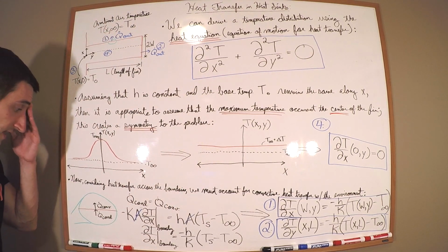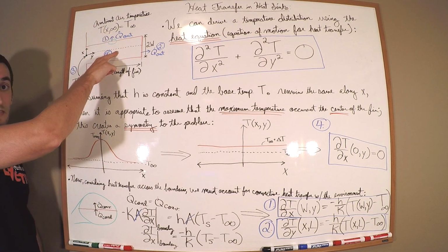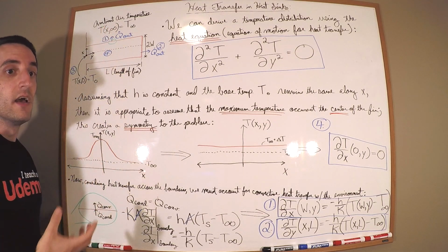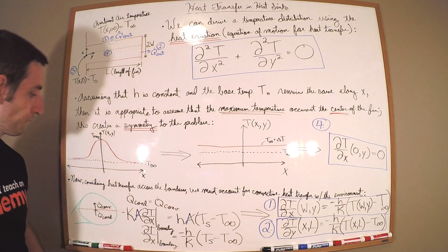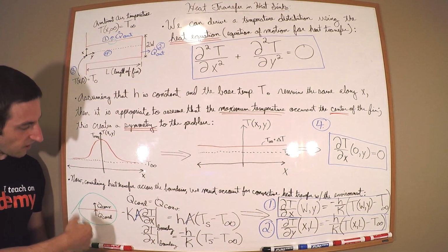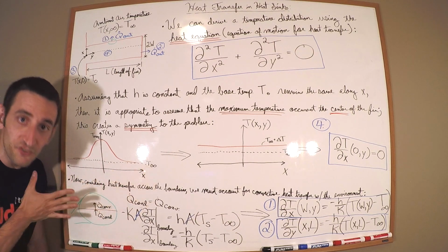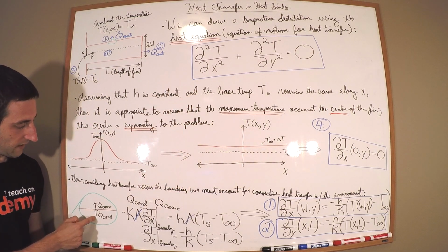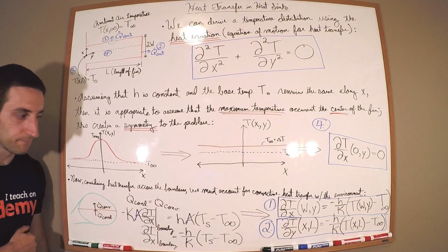And what you find is that the heat that's flowing, this is the max temperature, so the heat has to flow out to low temperature, right? The temperature differential drives the heat transfer. We find that conductive heat transfer is going to flow towards the surface. The air is going to pick up that energy, flow away, dissipate it. So we're going to have conductive heat transfer up and convective heat transfer out.